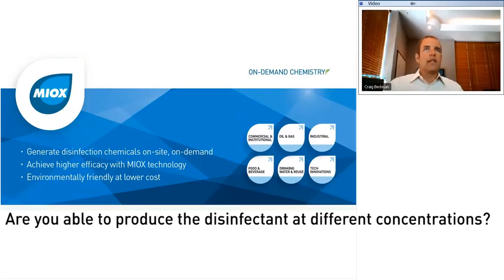And since you're taking the mixed oxidant or the sodium hypochlorite output and injecting it into another stream at a very, very dilute level, really it doesn't matter if your concentrated oxidant is at 0.5% or 1% or 5% or 10%. It's simply the size of the chemical feed pump that injects that fluid out into your facility, because we don't have any applications that use the chemistry at anywhere near that dosage.